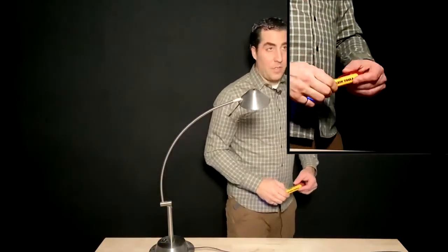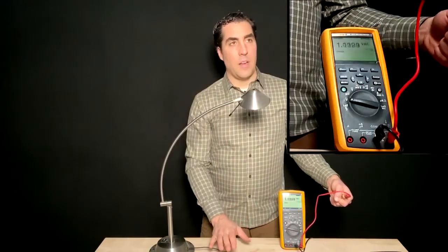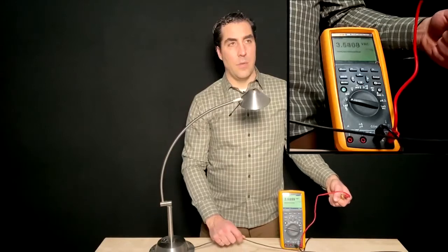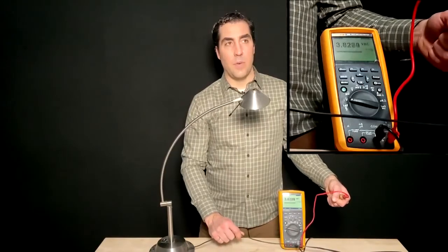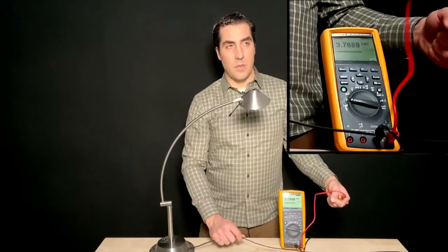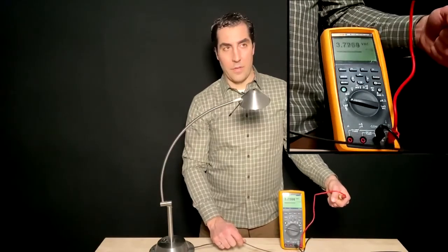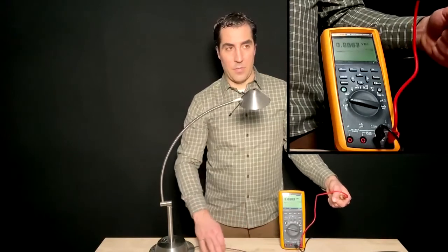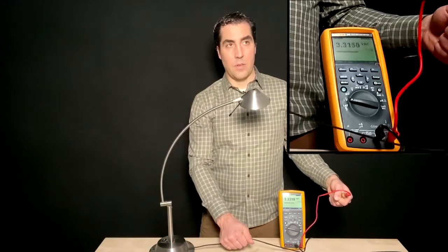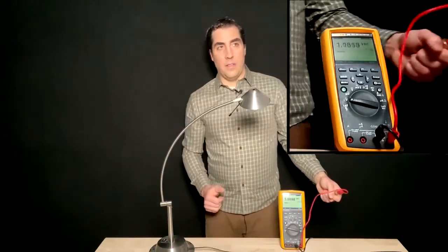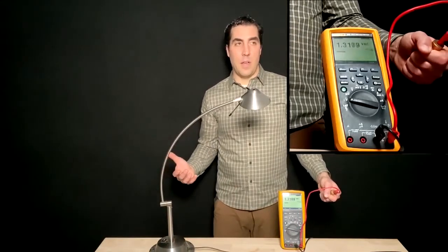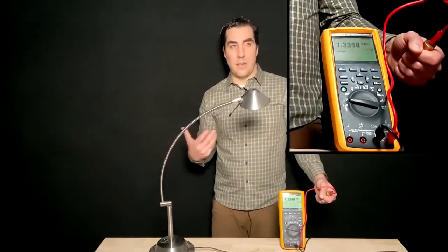So how much voltage? As I bring my hand closer to the cord, right, we see there are almost 3.5, 3.7, 3.8 volts coupled on the surface of my skin, even though this lamp is turned off. But again, there's electrical pressure up to the on-off switch here. So as I'm holding this cord, it's up to 3.3. As I step away, there's about 1.2, 1.3 volts, just based on the lighting and the different things that are currently around me.